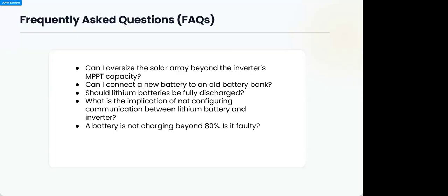But for other brands, because somebody called sometimes and told me his experience when he did that, when the solar array was increased beyond the capacity. Beyond the capacity, not in terms of voltage now, because you should not exceed the rated voltage. If you do that, the charge controller is going to get damaged. Whether Fronius, whether any product is going to get damaged. If it's well protected, then it can tell you maybe over voltage or something. But you must have been warned in the manual, which I'm sure of, that you should not exceed the voltage.